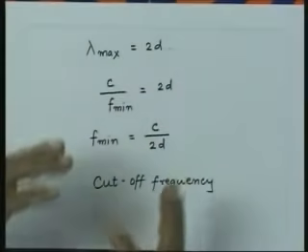So, even if the waveguide is capable of supporting different values of m, it will depend upon the frequency whether that value of m will be acceptable or not, because whether this condition, that the frequency is greater than the cutoff frequency, is satisfied or not. So, this is now a basic picture of modal propagation in a bound structure like a waveguide. We will elaborate on this, and following this we will try to see another mode when we meet in the next lecture, and then we will go to the more complex structures like the rectangular waveguides.